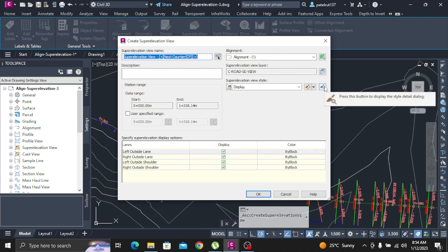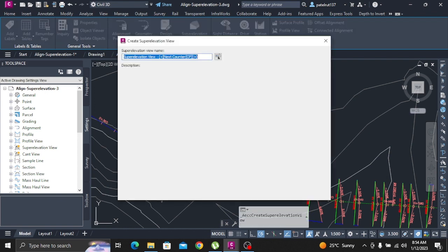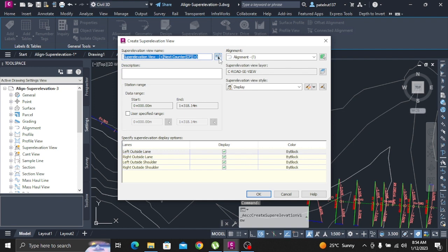Move the grip to station 0+900.00. Click to place the grip. Pan to the transition out region of curve point 4. Near station 1+147.69, Control plus click the light red curve. Hover the cursor over the grip at station 1+148.59. The cursor snaps to the grip, and a menu of options is displayed.